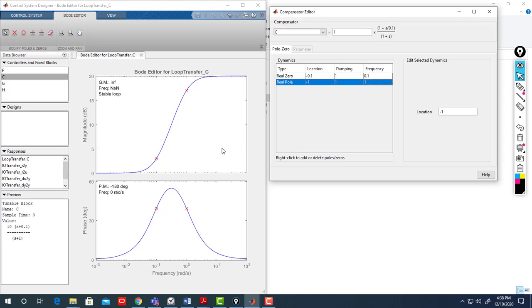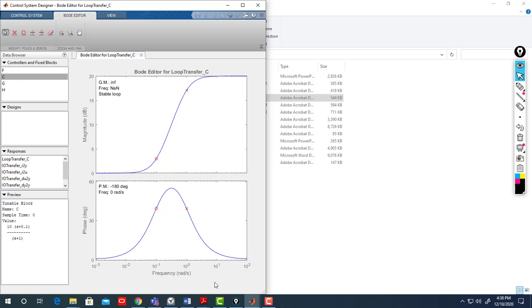On a logarithmic scale, multiplication becomes summation. So minus 20 and plus 20 cancel each other and become 0. And the same for the angle. Remember it was 0 to minus 90 to plus 90. So after adding the pole, minus 90 plus 90 returns back to 0, and that's what you could see.